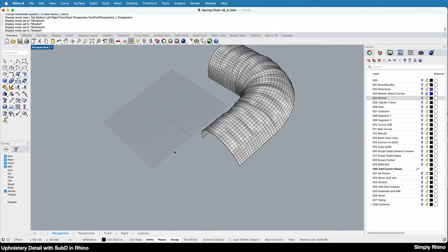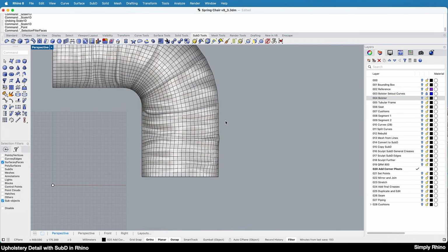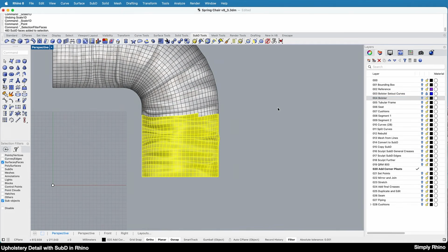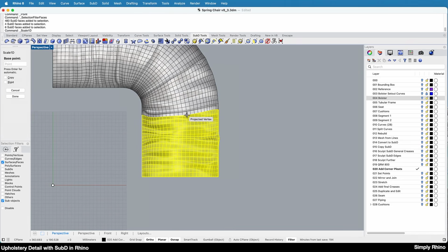Because the bolster isn't symmetrical and yet I've modelled it so, I now need to lengthen the one edge to match the NURB solid that I'm using as a template. The most sympathetic way of doing this is to scale a number of faces rather than merely lengthening the edge. I'll go back to the plan view on the bolster and turn the project constraint on. Then I can enable the face filter and select the relevant faces that I'd like to scale.